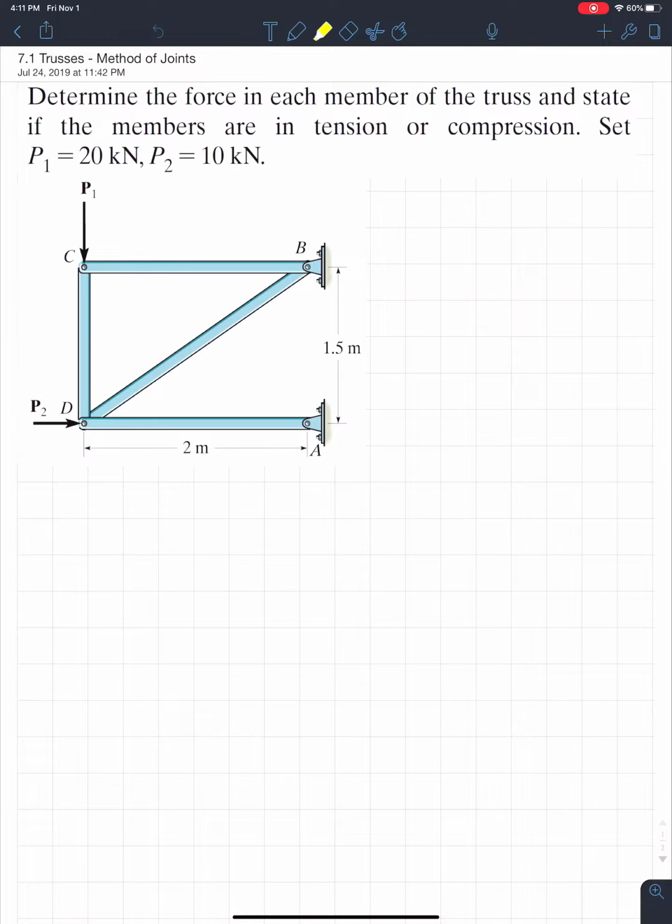When I taught the lab for this a year ago and then 2 years ago and so on, I find that every student knew exactly what to do. The only thing that would mess them up are them switching their signs. And as you guys will see, for trusses, there's going to be a lot of members. Sometimes you can very easily get confused and switch up a sign. And if you switch one sign, so let's say something is positive and you switch it to negative, it's going to mess up your whole truss. So it's very important that you have a standard sign convention. And again, I'll show you which one I use. And from there, we can go on and hopefully you guys can stick to mine, or if you guys believe that yours is the best, then by all means, go for it.